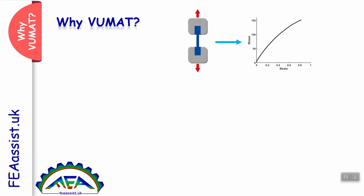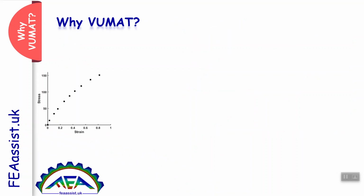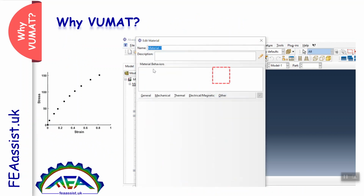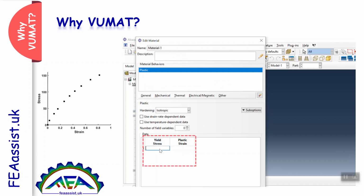Consider you have a sample and you want to apply load to it in a dynamic way and predict, by modeling and simulation, the mechanical response, the stress-strain behavior, or the load displacement curve. The first strategy is that you have some points of your stress-strain or load displacement curve from the lab or published experimental results. Then you can easily go to the Abaqus property, define a new material, go to the plastic behavior and enter those points like this. Abaqus interpolates between these points and predicts the behavior of the material at all points. This is the simplest way, but it is not precise because of interpolation.